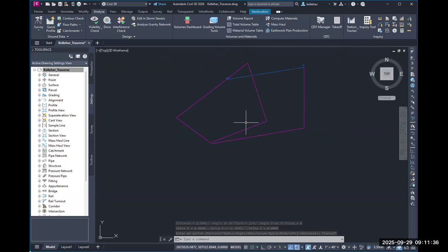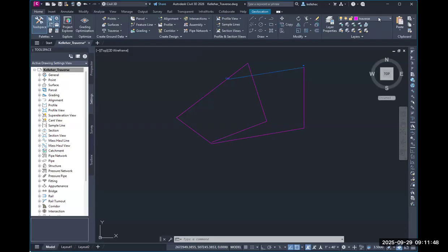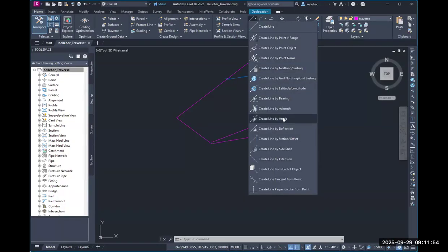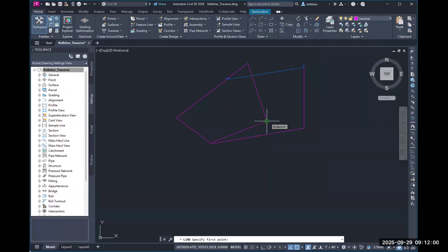All right, so you have your traverse drawn, but how do we rotate it into place? This is where you want to use your lines associated with your measurements to Colton Chapel. So I'm going to stay in traverse, but you may want to change these lines eventually. You're going to go to, again, create line by angle. Wherever points you cited the Colton Chapel spire.